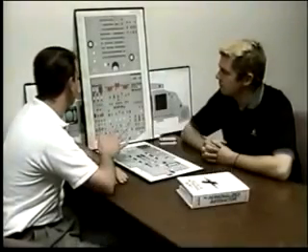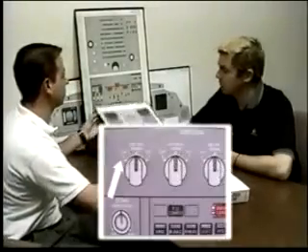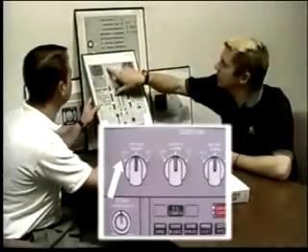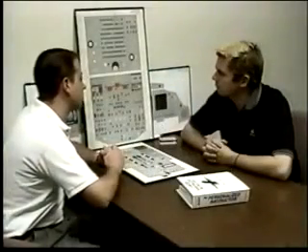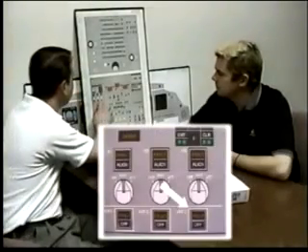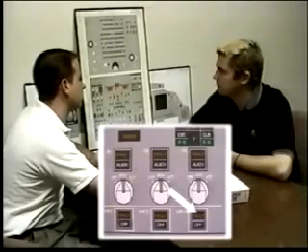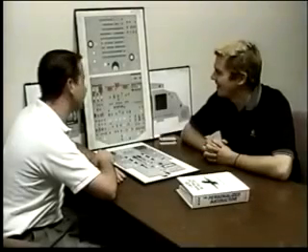Okay. Either scenario, ECAM's going to direct you to do what? It's going to direct me to come down and take attitude and heading captain on 3. Now you lose the first officer's speed and baro reference. What's failed now? ADR 2. You look at the overhead, you see a steady fault light on ADR number 2. Yep, I see that. That's an indication of what?